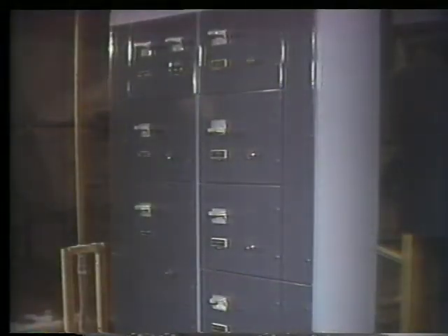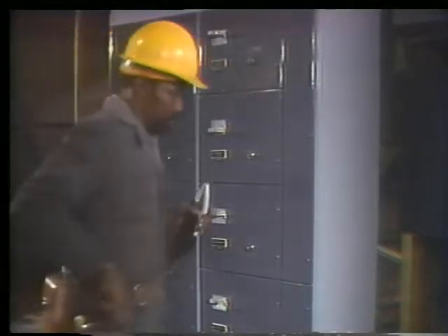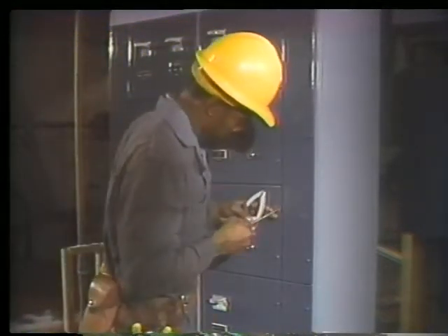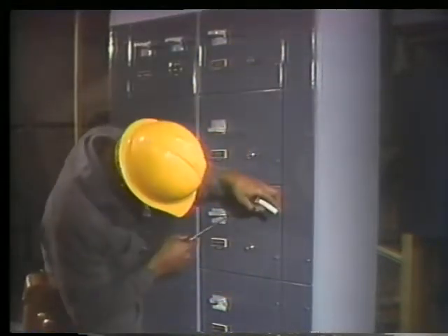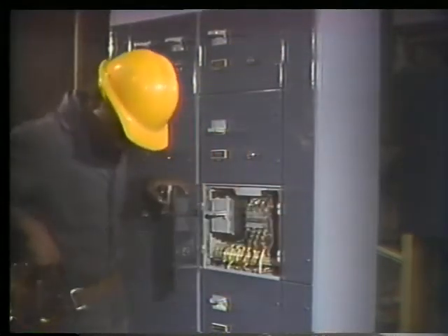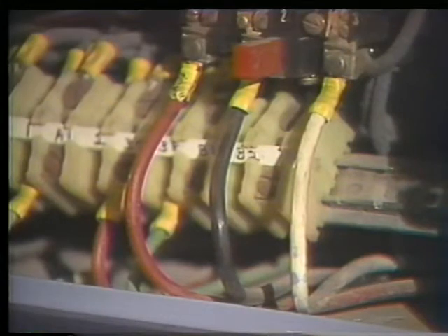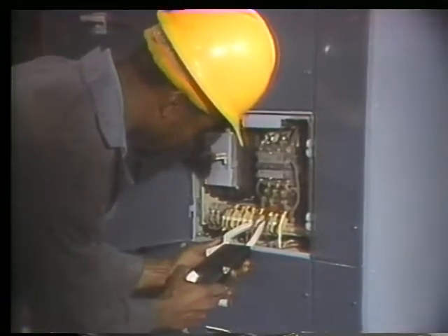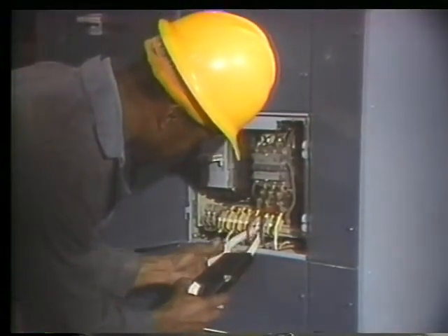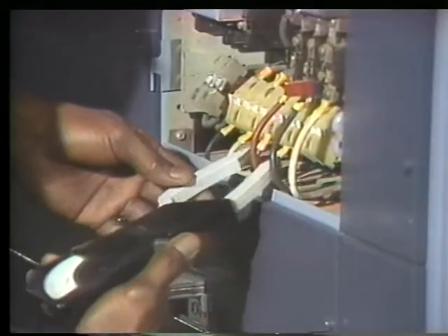At the motor control center, the electrical current which flows to the motor can be checked for a balance of phases. By unbolting the front of the control center's enclosure, the controls are revealed. These three conductors supply the motor's power. So we use a clamp-on ammeter to check the current flow in them. In other cases, permanently installed ammeters may be used.